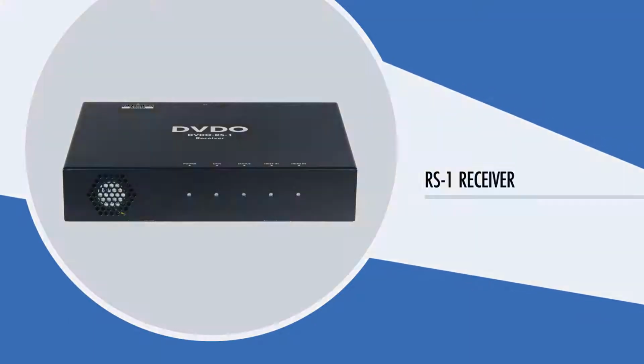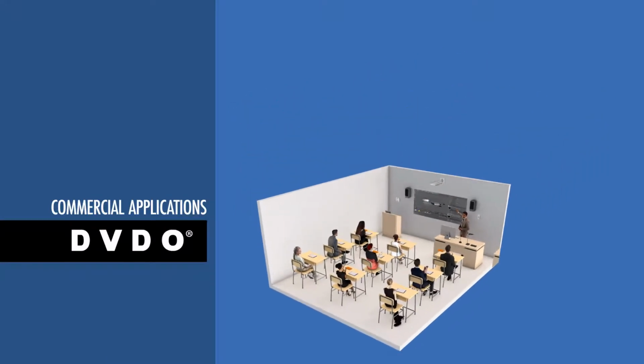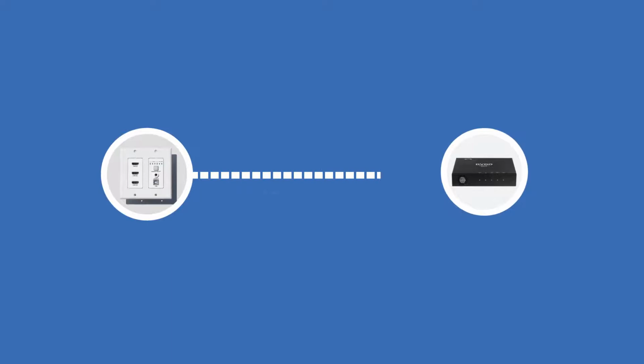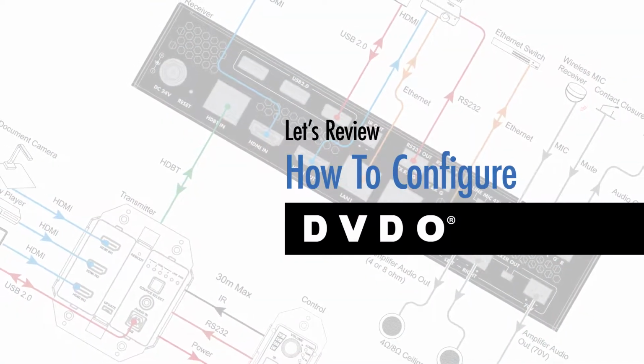Employing the worldwide HDBaseT standard, this robust system covers distances of up to 100 meters or 330 feet between the wall plate transmitter and receiver via a single Ethernet cable run. So even for large venues like auditoriums and boardrooms, RS1 delivers reliable and secure high performance. This video will walk you through the steps to configuring your system once installed.